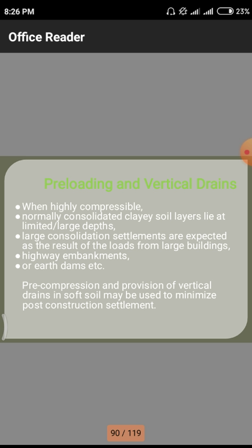For the slab itself, we are using hollow core slabs and lightweight concrete materials like fly ash bricks, and other lightweight structures like aluminum panels. In the case of wooden structures, for the wooden members we simply use plywood. All those methods are to decrease the total load acting on a particular soil, so indirectly we are decreasing the settlements occurring on the soil. We need to think like that.